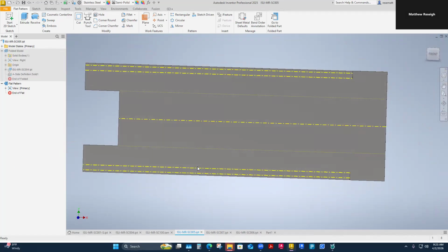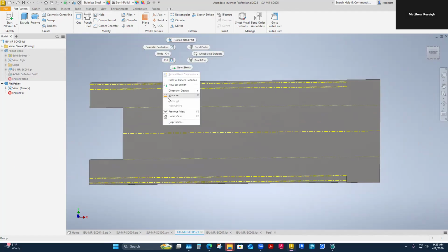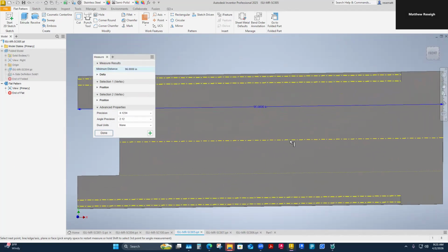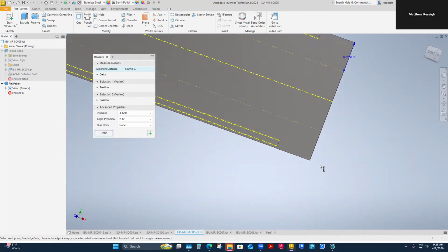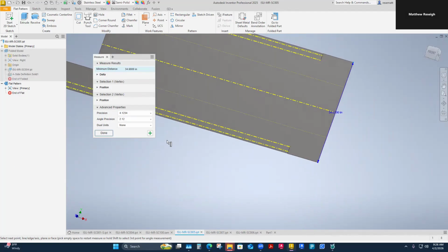The other interesting thing to note, if you haven't worked in the industry a lot, is to be aware of the size of this piece of sheet metal. Is it even sourceable? I've designed it to be one piece, but double check yourself on your flat patterns. This thing is 96 inches by 34.68 inches. Especially with large flat patterns, you need to decide quickly in your design process whether you are designing to use available sheet sizes or if you have made stuff too big.